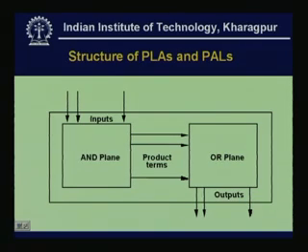Last day we have seen that programmable array logics can be constructed by defining two planes, the AND plane and the OR plane. The AND plane generates all the product terms, and the product terms are fed to the OR plane, which generates the output.